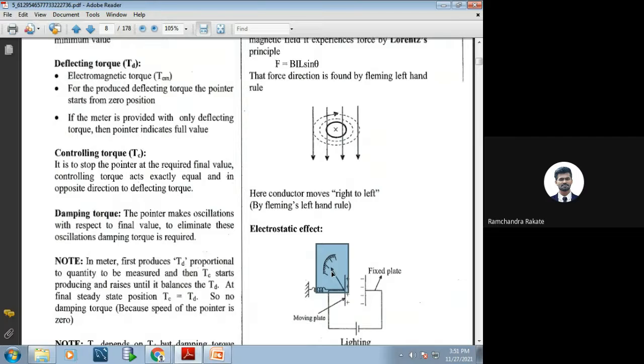While performing any particular application, forget about the application. In a real time scenario, if I'm using a particular instrument for my measurement, and I observe the analog instrument has a certain kind of deflection without any live condition, are these instruments good to use or not? No, sir. It becomes an error. Whatever the amount of deflection, it will get added to my measurement.